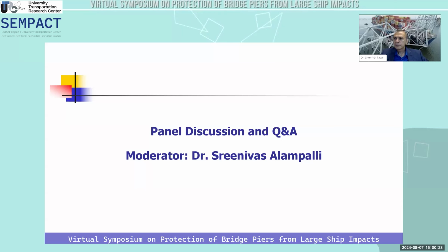And I think this is also something that gets a bit overlooked, but there should be some minimum threshold, so we don't have circumstances where we have piers with very little vessel impact resisting capability. This is also something we could think about as a baseline level. And we, in some sense, have that, particularly in inland waterways where we have the flood condition with an empty barge. But I think there's arguments to be made that we